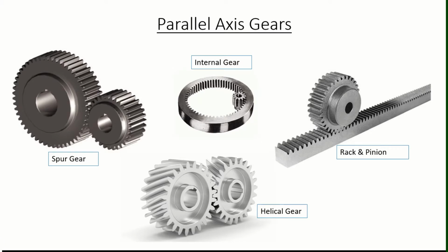this category. So starting off with the spur gears, these are the gears which have the cylindrical pitch surfaces, and they're also called the cylindrical gears. The spur gears belong to the parallel shaft group, as we just looked at in the previous slide, and these are the cylindrical gears with a tooth line that is straight and parallel to the shaft. Okay, so the spur gears are most widely used gears, and they can achieve very high accuracy with relatively easy production processes, and that's also a key factor in using these spur gears.